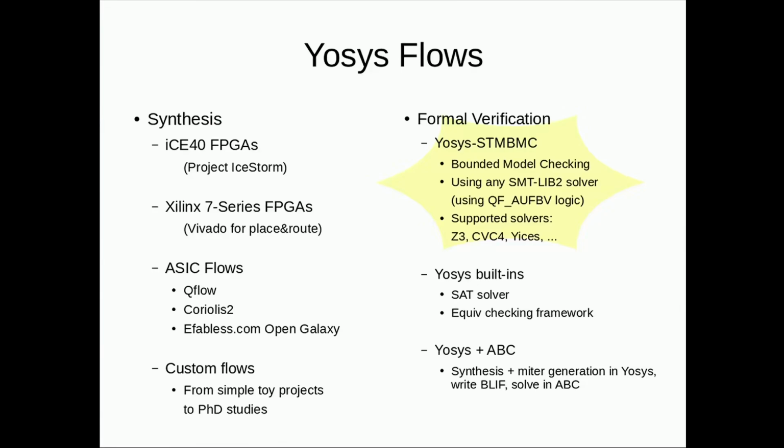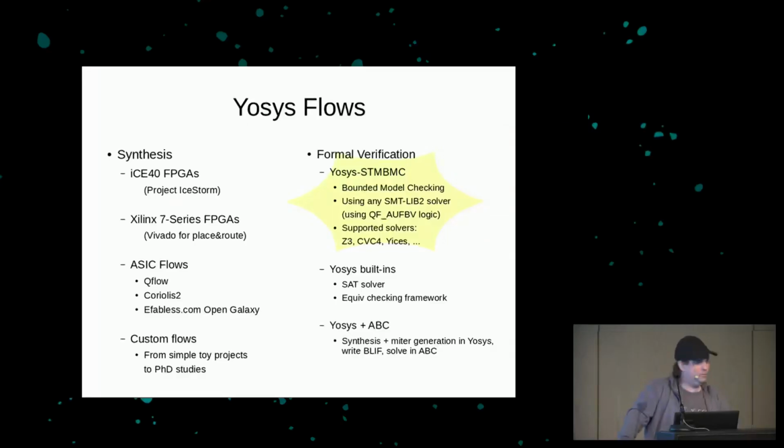On the formal verification side, we have Yosys SMTBMC, which is the thing that I'll be talking about today. But there are also some other verification flows available in Yosys. For example, there are a couple of built-in commands in Yosys directly that can be used for certain verification tasks. There's a built-in SAT solver that you can use for some things. There is an equivalence checking framework.